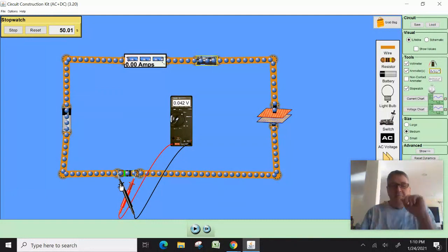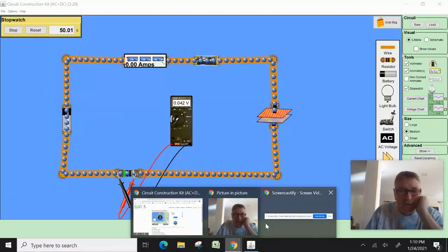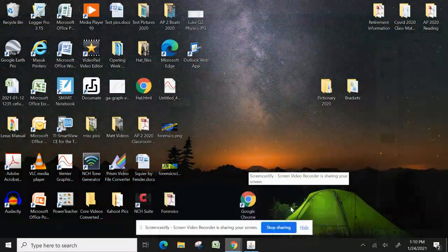Okay, so that simulation is the first circuit. If you filled in the columns, you can have your data. Oh, by the way, notice that the current is no longer flowing. The current's flowing as we're charging the capacitor. But once the capacitor is done charging, or almost done charging, the current dropped off almost to 0. And again, we'll see this if we do some other simulations. So I was just trying to show you the basic setup of how that works. Hopefully you're able to go back and do the rest of them, but we'll see.